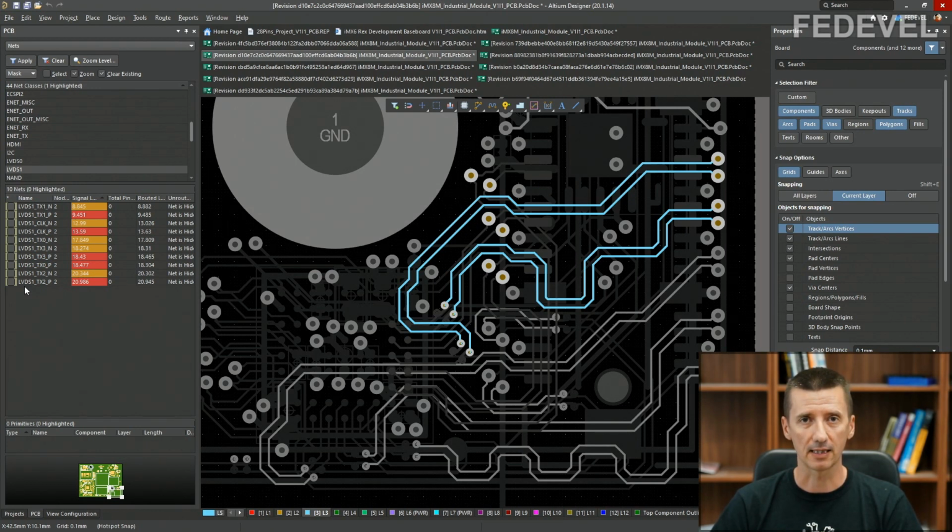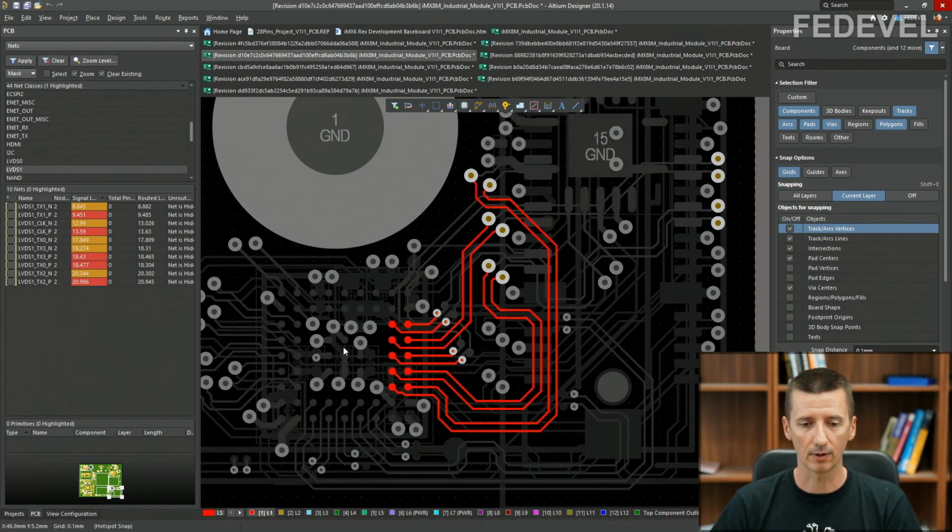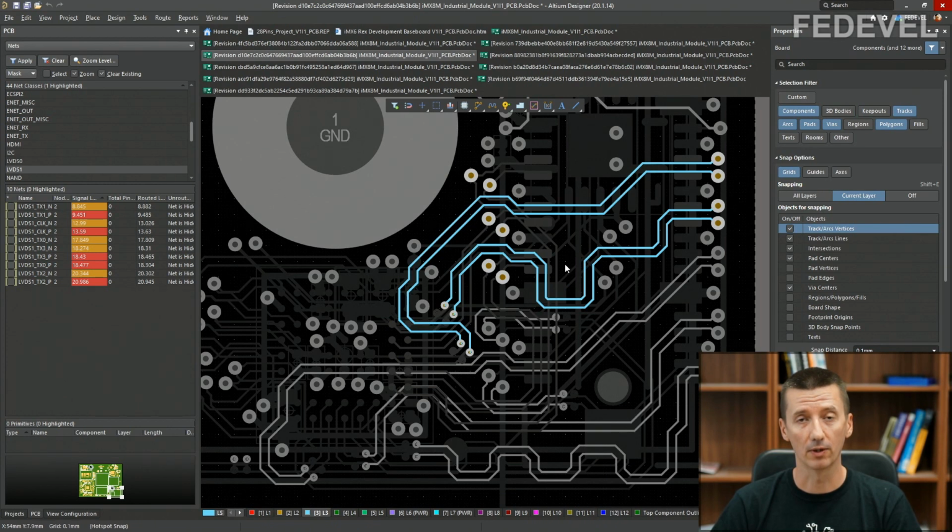One of the reasons is the length in the vias will be exactly the same, and also keep in mind that signals travel at different speeds on the top and bottom layer and inside of the PCB. So if you route your signal only on the top layer and bottom layer, then it may travel a different time than the signal which will also be using layer 3.